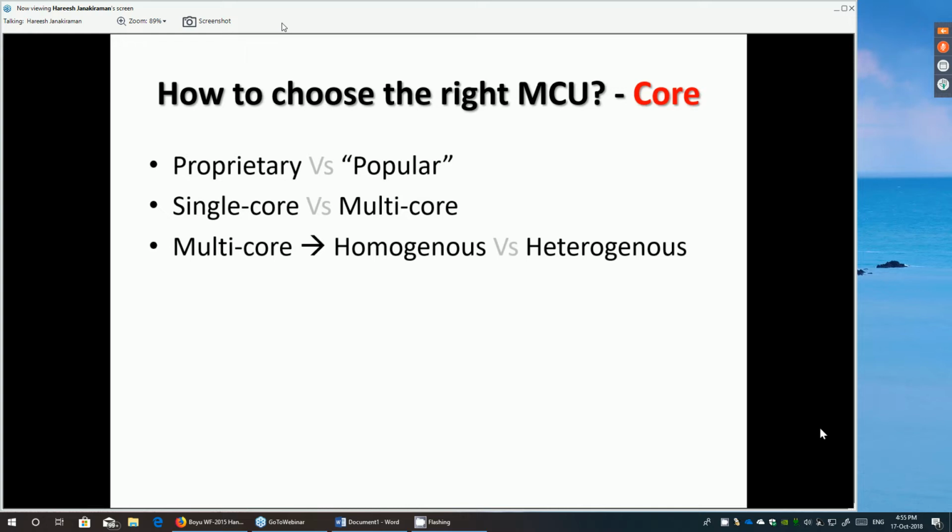So for every sample of the voice signal, I only have 125 microseconds to convert it into a digital signal, to process it, filter it, compress it, and transmit it. I only have 125 microseconds. So if I use a 8085 processor, it may not be able to do this in 125 microseconds, which means I cannot do this signal processing in real time.